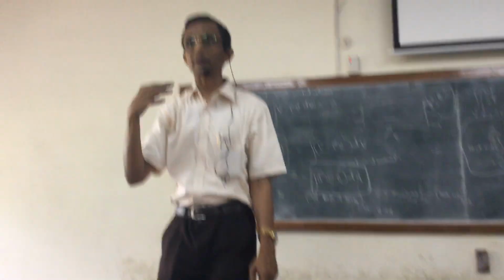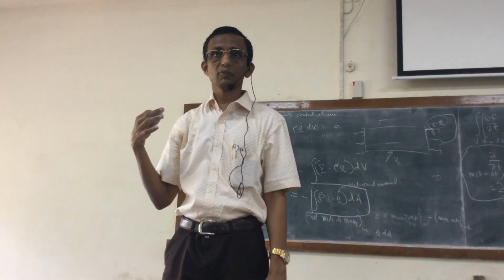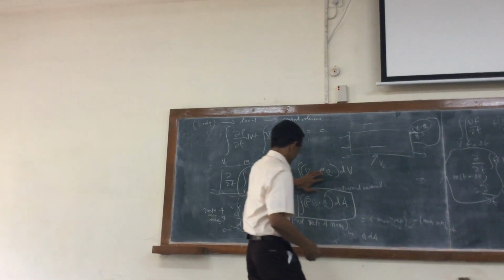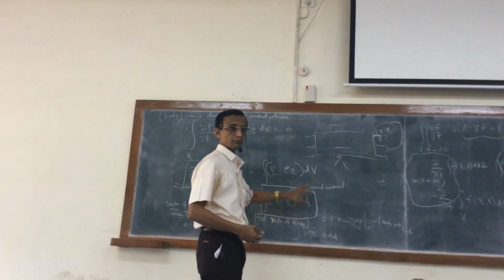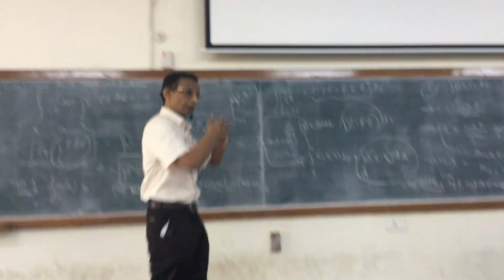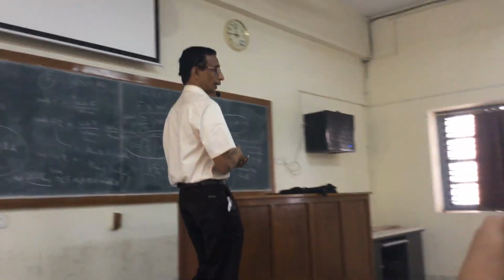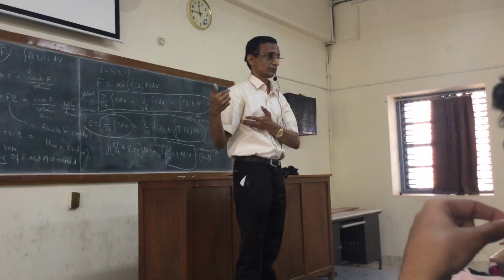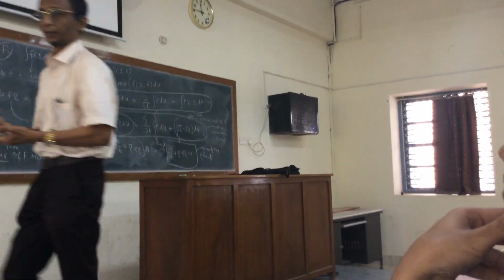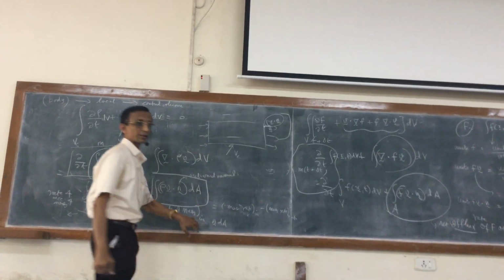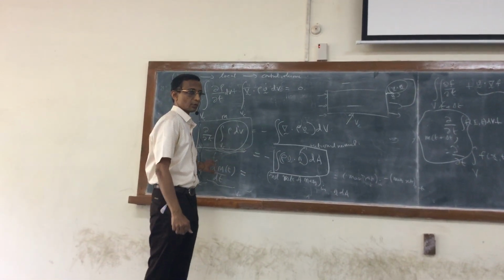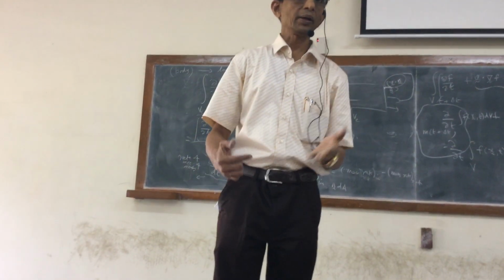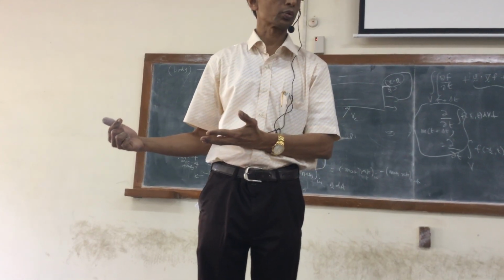So that effectively gives the mass flux at a particular location. So when I integrate it over the entire control area, or the area enclosing the control volume, then I get the net mass rate out. When I take the negative of that, I get the net mass rate in. So you get the very well-known formula, rate of accumulation of mass is the net rate of mass in minus net rate of mass out.